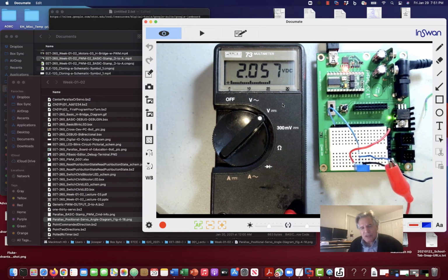Some of the first analog to digital converters, what they did is you built a current source in your microcontroller and you turned it on and you charged a capacitor. And if you do the mathematics, running a current source into a capacitor will make a nice linear ramp, like a sawtooth waveform.